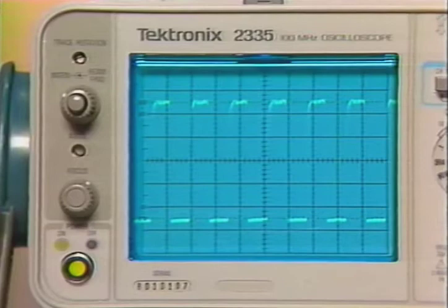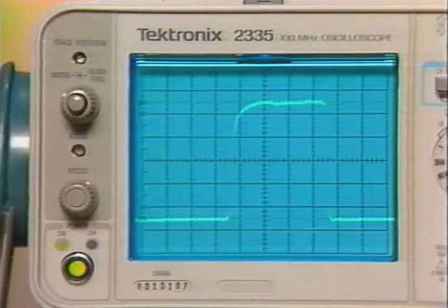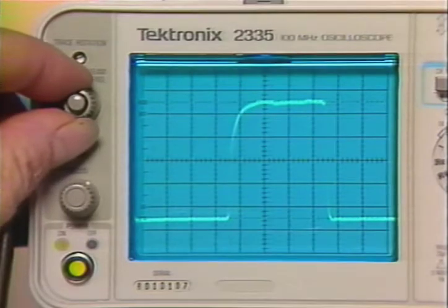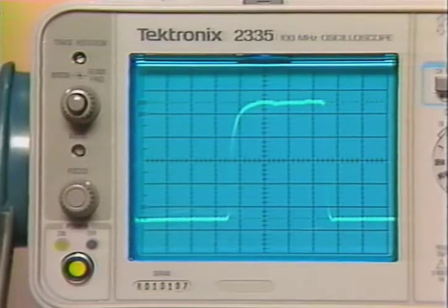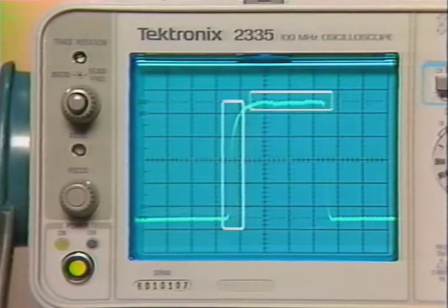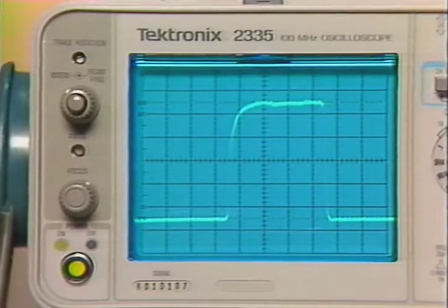An intensity control is necessary because you use a scope in different ambient light conditions and with many different kinds of signals. A slowly moving spot is brighter than a fast-moving spot. If the spot is always moving fast and repetition rate is low, the intensity must be increased. In another example, the slower-moving horizontal components of square waves will always appear brighter than its faster-moving vertical components. So the intensity control may be adjusted depending on which parts of the waveform you want to see clearly.